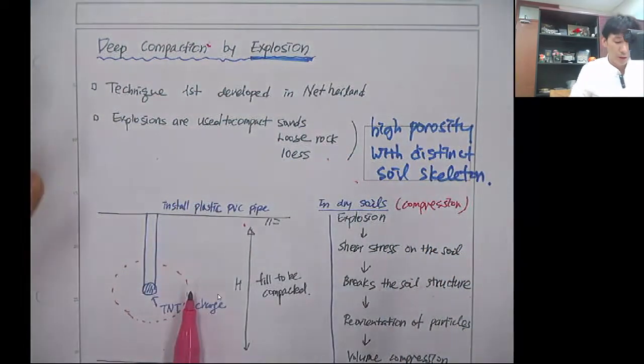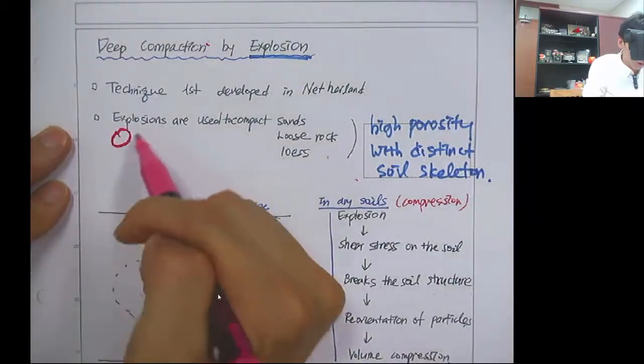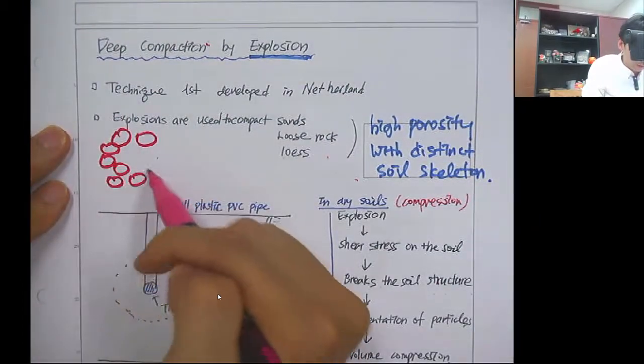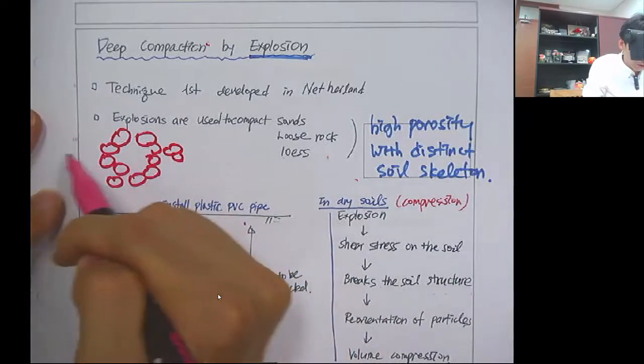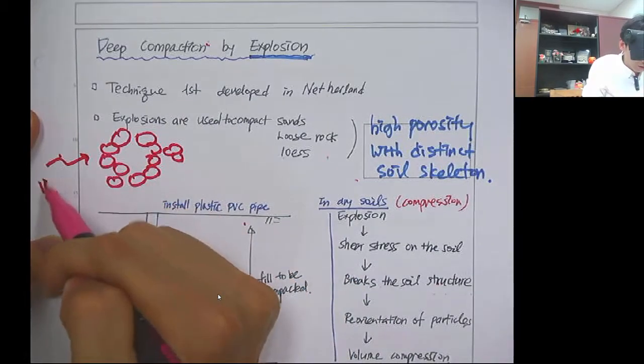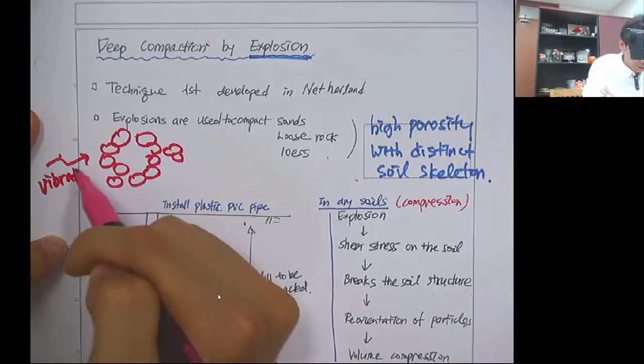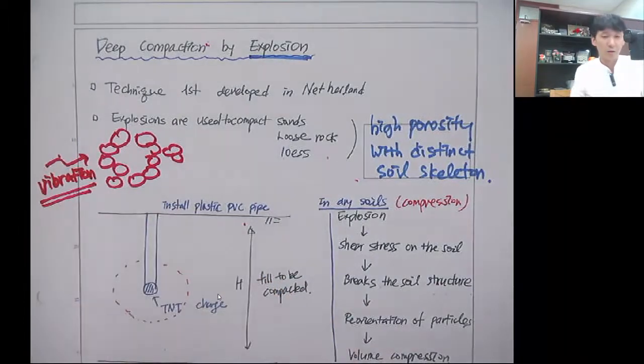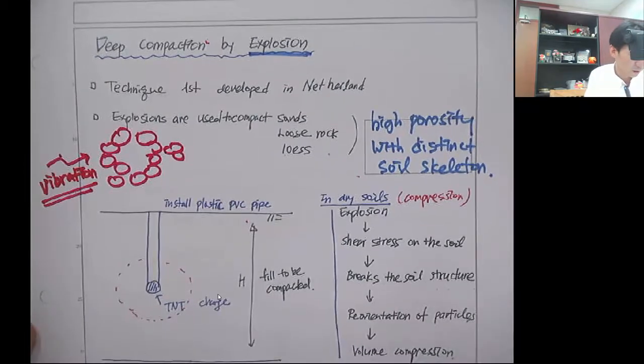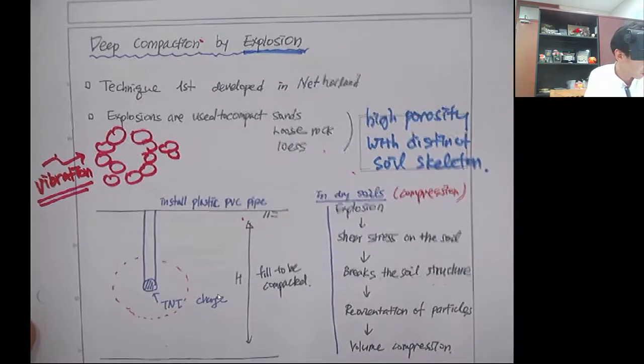So it's very effective when you have honeycomb structures that are very collapsible, or a loose sandy structure that can be densified very easily using vibration.